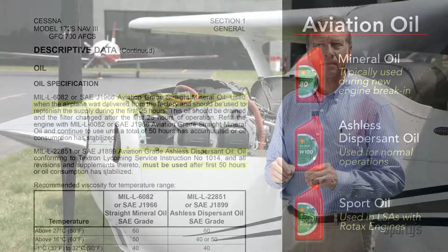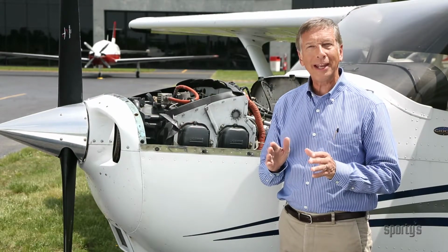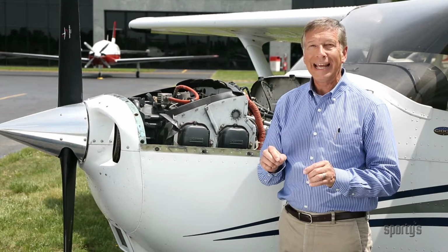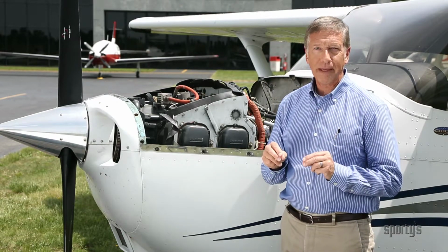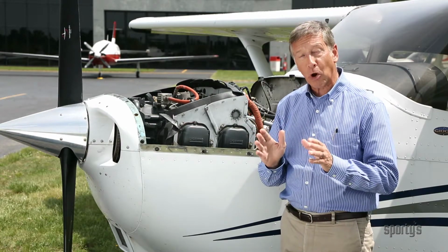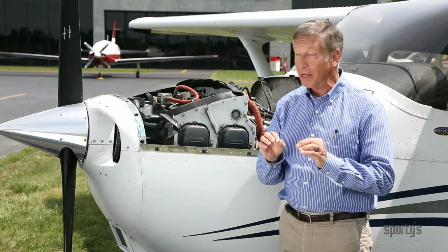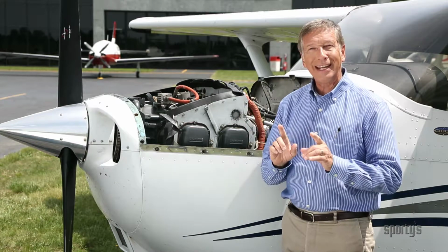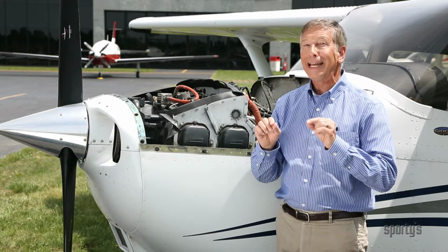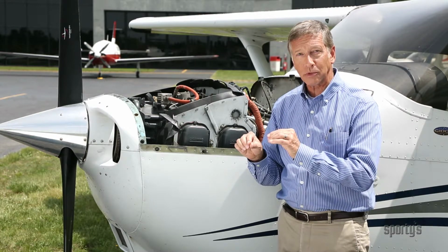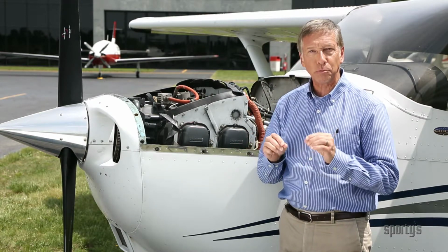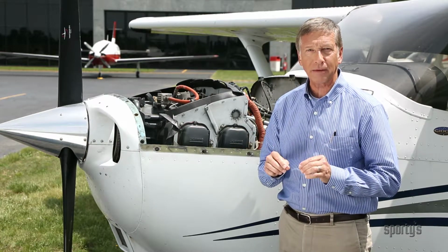Another reason airplane engines are so reliable is that they have a dual magneto ignition system. The magnetos generate the spark, which ignites the fuel-air mixture in the cylinders. The magnetos allow the engine to operate independently of the airplane's battery and electrical systems, and is one of the redundancies built into the airplane for safety.